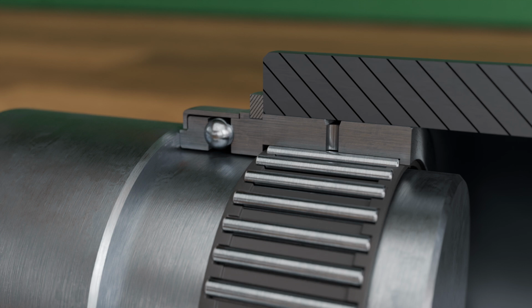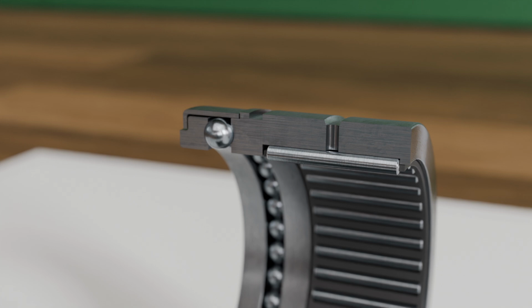Such combined needle roller bearings are available both with cages and in a so-called full complement thrust ball design, where the balls lie directly against each other without a cage. Due to the large number of balls, this design can absorb particularly high axial forces. However, because of the direct contact between the balls, only comparatively low speeds are possible.